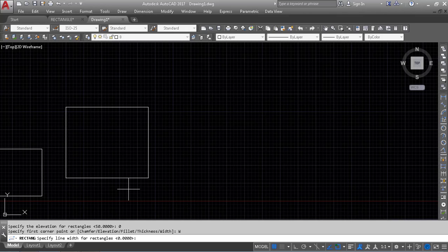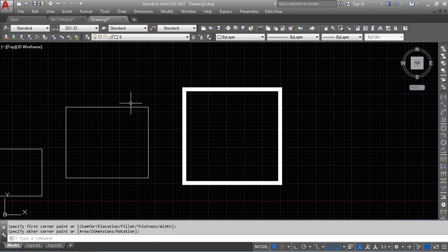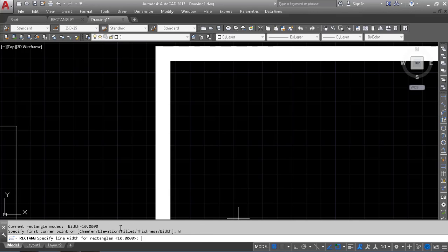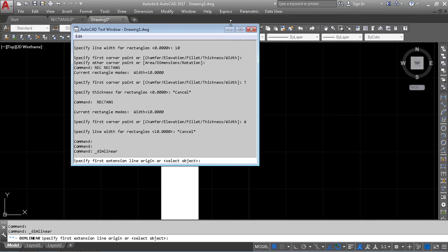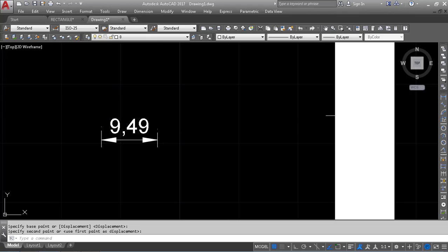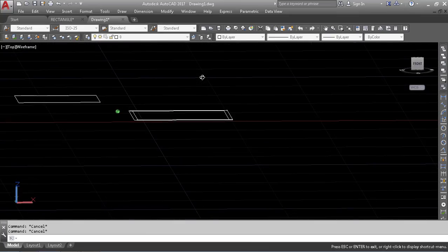But if you are making a 3D object for visualization, so to make the object easy, you need to make thickness. For example, I am putting one radius, and now I am making it have one width. How much? While I was making, I put width 10. This one is width 10. Because it will not snap, I am putting just some example, means without F3. I am going to close the snapping, and I am going to just approximate from this point to this one. Move. Look, this is 9.5 because I took the nearest point. So this is 10.